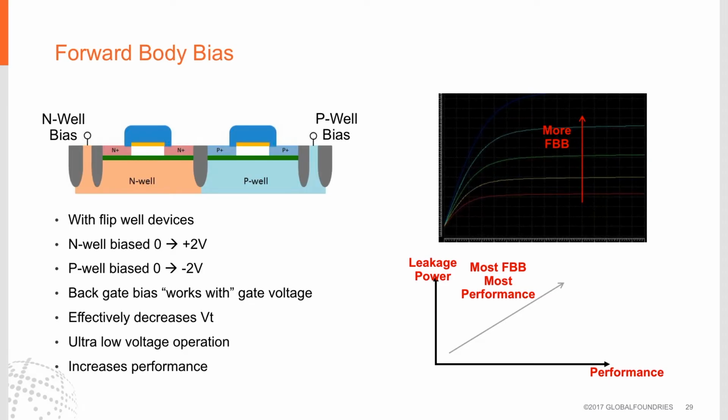In actuality, this 2 volt limit is not a hard and fast limit. The back bias can exceed these voltages, but the modeling is only accurate at this point up to the 2 volt limit. Beyond that, the model begins to become a little bit less accurate.